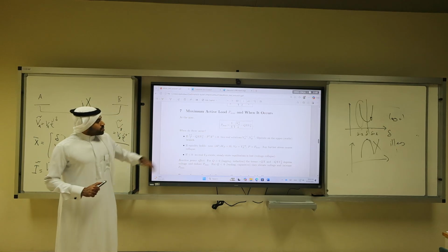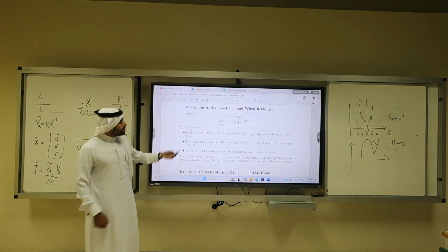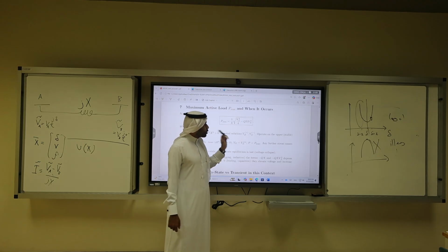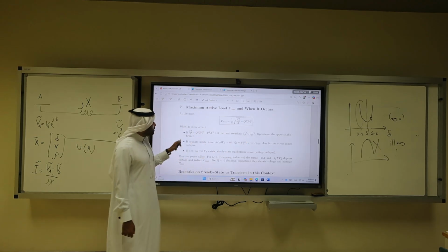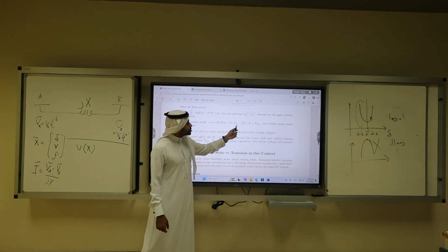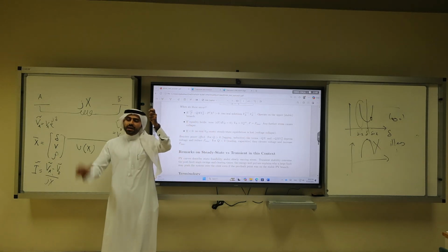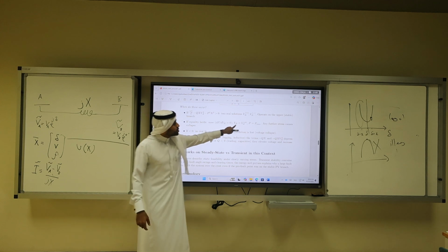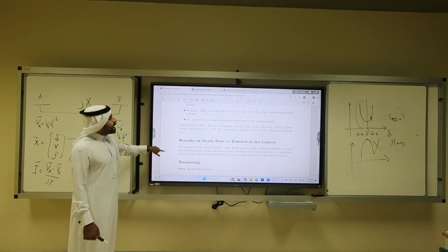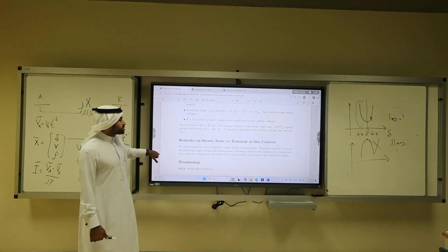Okay? So when does the maximum power transfer occur? It occurs if this is greater than 0 and there are two real solutions, not complex numbers, operating in the stable branch. And if this equality holds, the derivative will be 0, so VB is equal to V critical, P is P max. So the maximum power transfer occurs at the critical voltage. So at critical voltage, we have the maximum power. And if it's less than 0, no real VB exists, steady state equilibrium is lost.